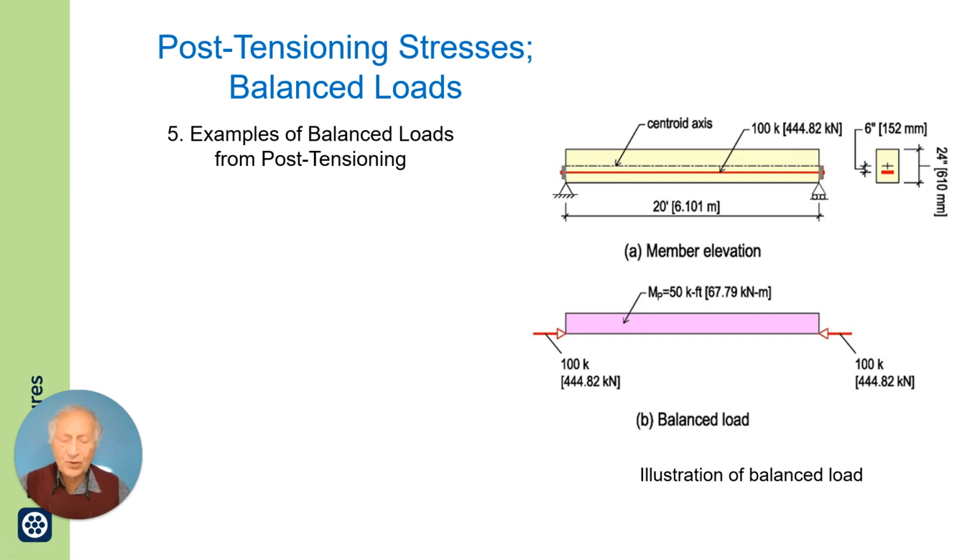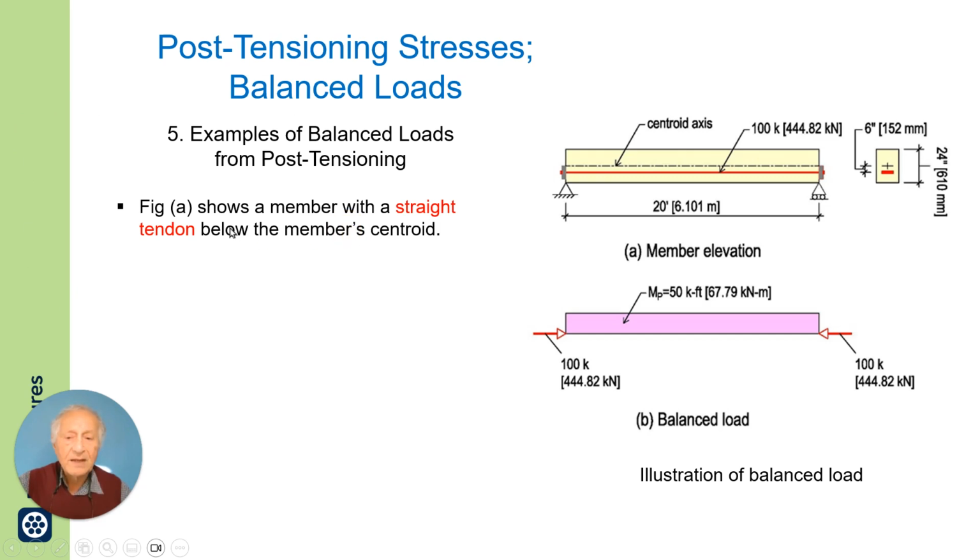Now, what I just showed you in the previous slide was the common practice, but we have instances where the design requires that the post-tensioning be somewhat different from a simple or compound parabola, like this example that I show here.